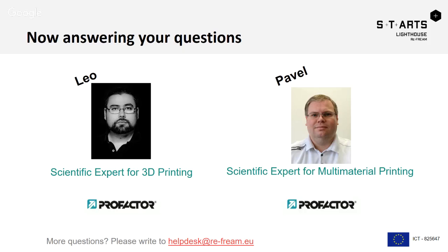You fill in a low viscous ink and print it through print heads, and you generate your objects in 3D via UV curable polymers. So printing with filaments is obviously not possible with PolyJet.